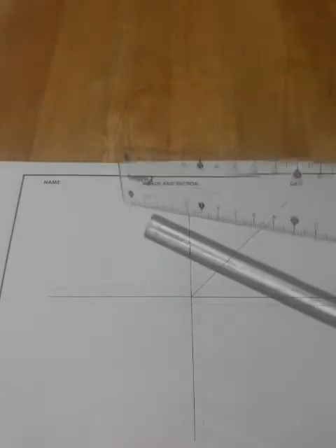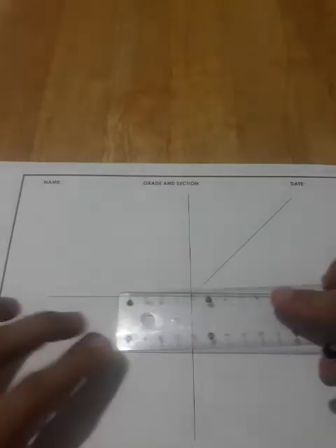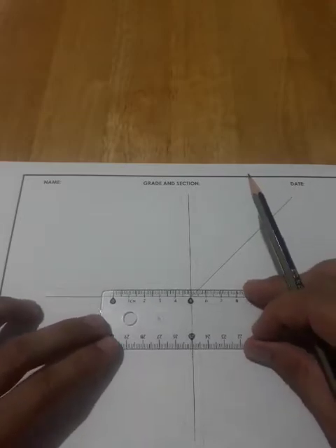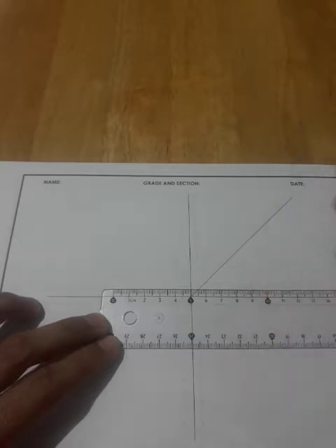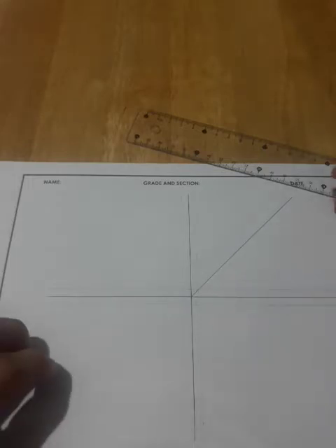So first thing to do is to identify, of course, the width and then the height, no? As we all know, on the top view, the depth and the width of the 3D figure is visible. So the total width of the object is 45 millimeters. So I will lay out the 45 millimeters. By the way, I'm already done with the offset lines, as you can see, and then the miter line. So I hope you were able to understand the previous demonstration on how to offset the lines for the vertical axis and then the horizontal axis, also the miter line.